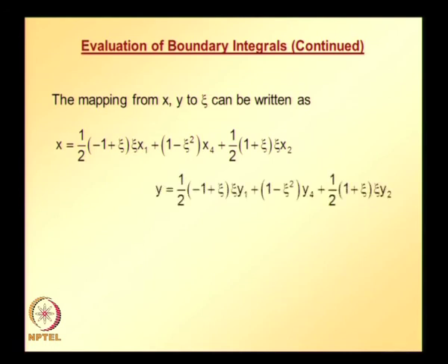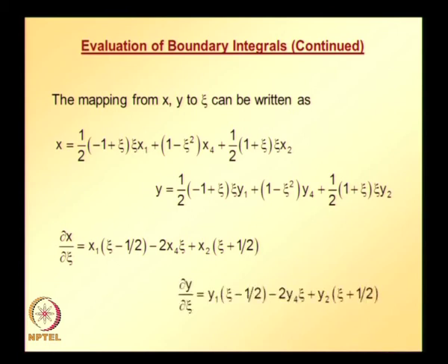Similarly, we can write the relationship between y and psi, and we can take partial derivatives of x with respect to psi and y with respect to psi. We also require the relationship between a differential element taken along side 1 4 2 of the physical element and a differential element taken on side 1 4 2 of the parent element.